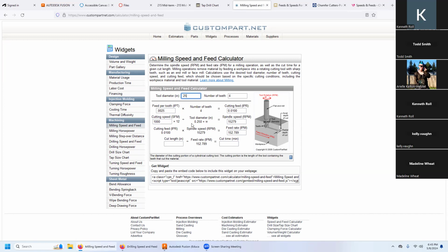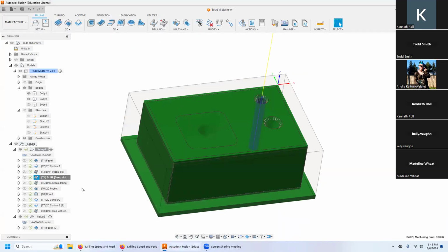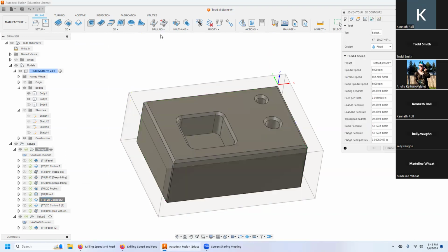So now that we've found the ideal ratio, we can just step the ratio down and say, okay, instead of that, we're going to set our spindle speed to 7,000. And they're going to suggest a feed rate of 70. Okay. So I'm going to come back here, find that. 7,000 and a feed rate of 70, which seems a little fast to me.